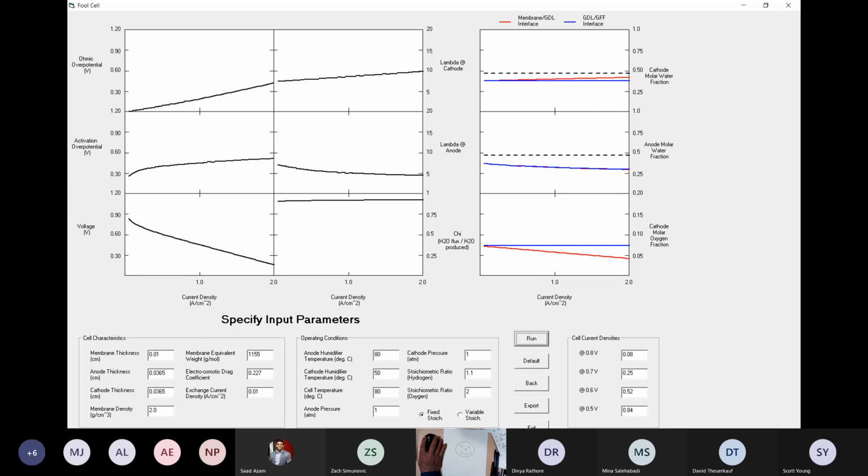You have to have enough pressure to run the gas through the fuel cell and then exhaust it on the outside. I can't remember if this is gauge or absolute pressure here. But it has to be at least 1 atmosphere of absolute pressure. And normally it's more because you have to force the gas through the flow fields.